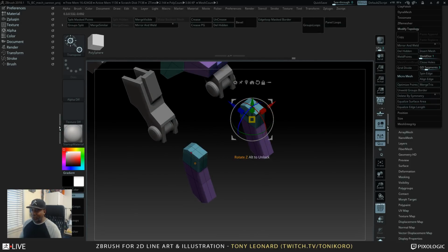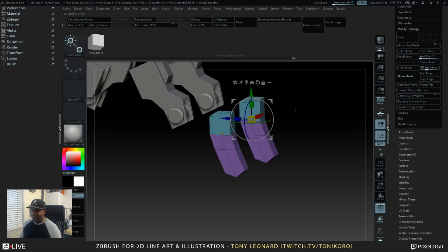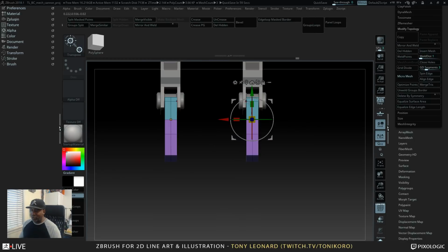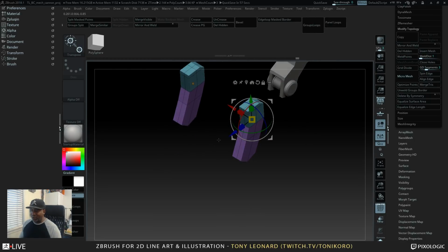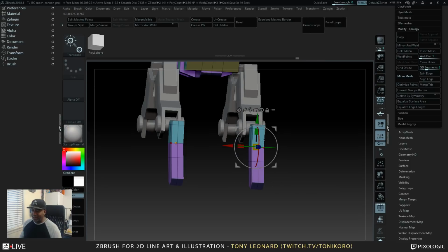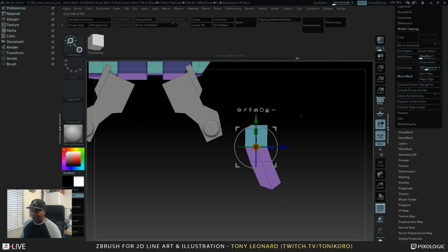And then you could probably flip it again, actually holding Alt and going all the way around, do a 180 there. So now it should be more local to the front, and of course the Z forward, the X, and the Y up. You can get it dialed back in so that you can start rotating stuff.